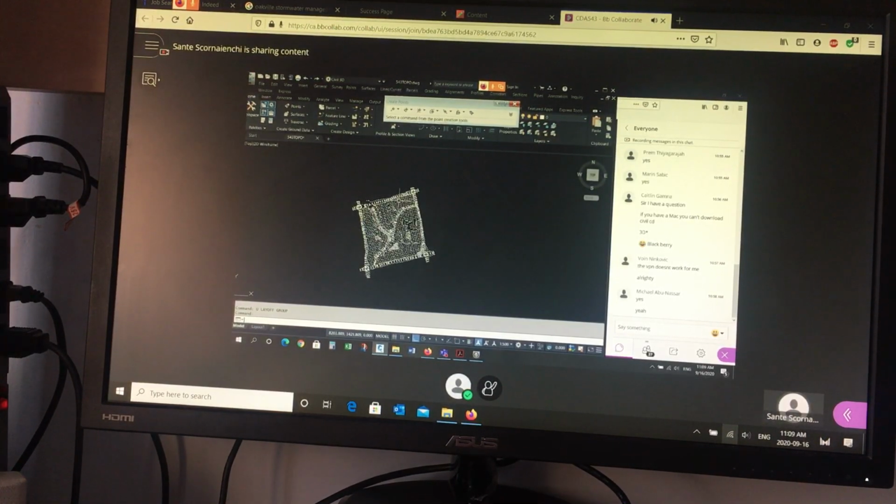So you want to make sure points of similar or same description are on the same layer. So we're going to categorize the points using AutoCAD layers. What layer should it be on? Well, if your description is centerline, go on a layer called centerline.